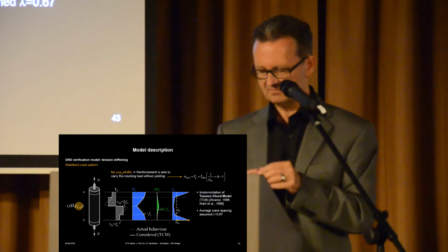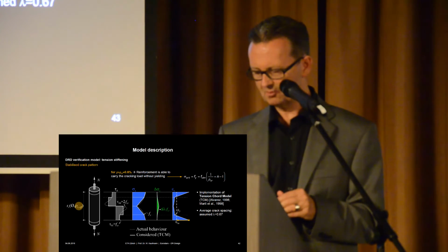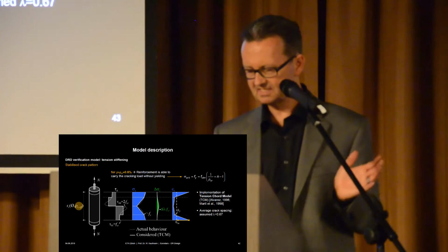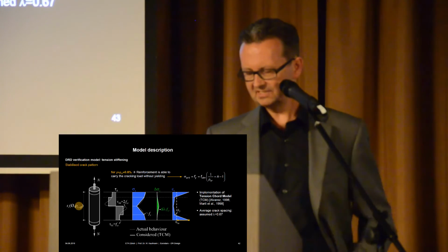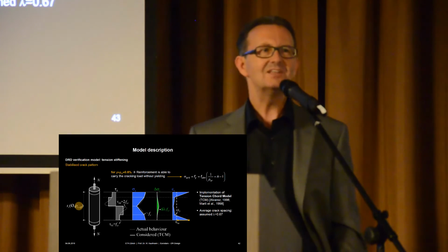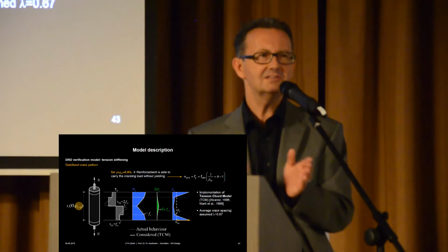If we can simulate this with this very simple model that captures the main effect, which is more or less a constant stress, which can be calibrated. It's about twice the tensile strength of the concrete before yielding, and then it drops after yielding of the reinforcement. It's not dropping because the rebar contracts at yielding, as some of my colleagues ultimately have written.